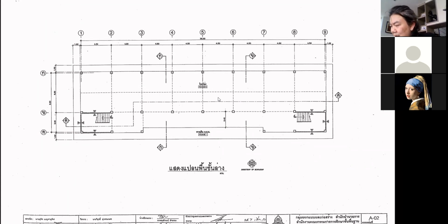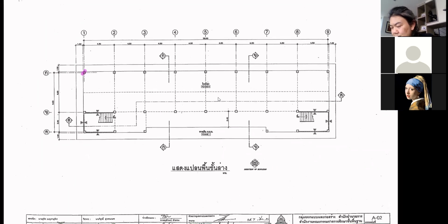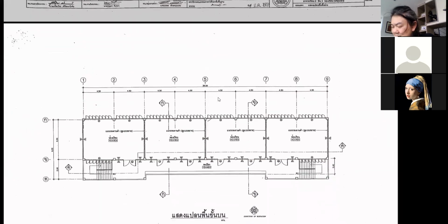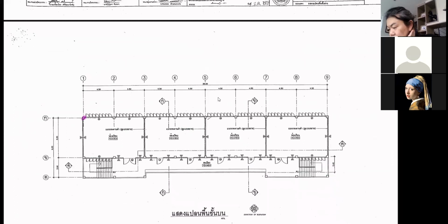When I was your age, when I started off in the design company, the first thing you need to do when you see the drawings is you mark the columns like this. So that becomes a column, so that you know where you can have your columns going up to support your structure. And that becomes the second floor. Just have second floor. Columns are the same.